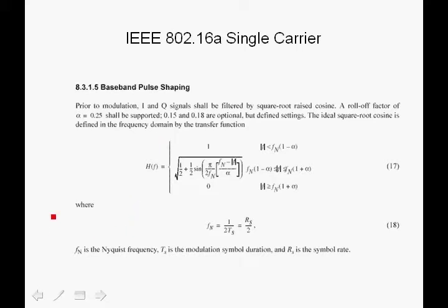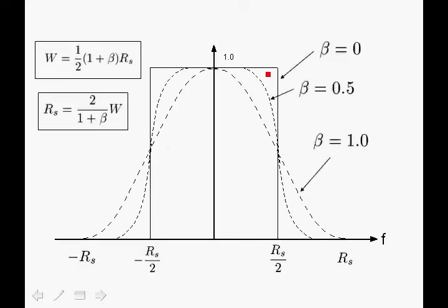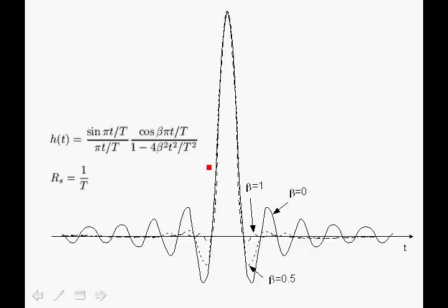So what we're talking about is very relevant in digital communications and is used quite often in single carrier systems, and especially in terrestrial microwave links. We'll come back to these equations a little later. Let's go ahead and take a look at the impulse responses of this family of pulse shaping filters in the time domain. This is a very important formula, which is the formula for the impulse response for the class of filters that are the raised cosine Nyquist filter.